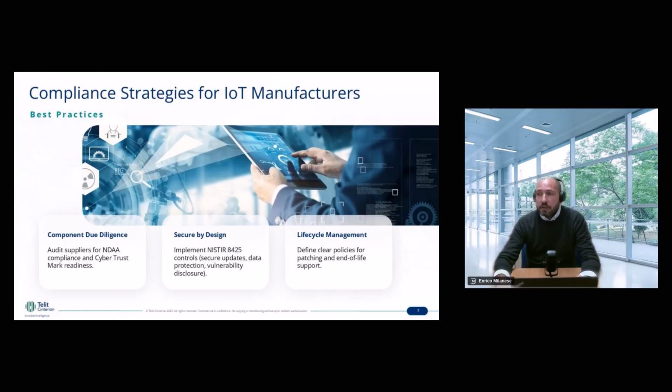So security configuration at hardware level, such as, for instance, secure boot and hardware root of trust, must be designed and implemented since the beginning and cannot be added later on without redesigning the system or creating specific new hardware and software variants, which results in increased production and maintenance cost.